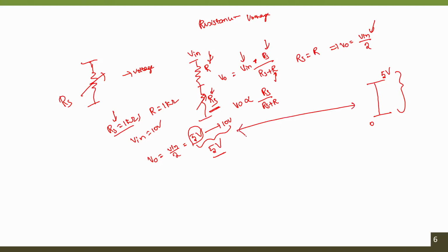But how can we compensate for this effect? The simplest way is to offset the output voltage from the resistive divider network by 5 volts. So, in order to do that functionality, we have different electronic circuits. Again, the design of signal conditioning circuits plays an important role. One way to remove this offset is by using operational amplifiers.